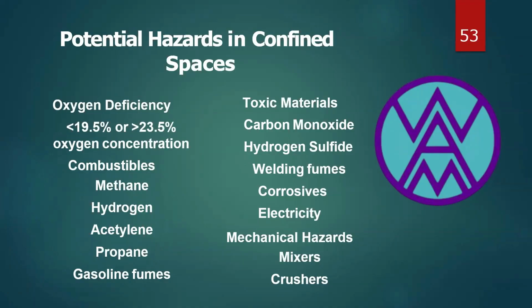Here we will discuss two things. One, the high risk of explosion. If you are working in a confined space and you are doing hot jobs that can ignite something, and there is some fuel available as well, and the oxygen level is higher, then there is a higher chance of explosion. As we discussed before, the fire triangle needs three things: oxygen, ignition, and fuel. So here the oxygen adds more and it will increase the fire.